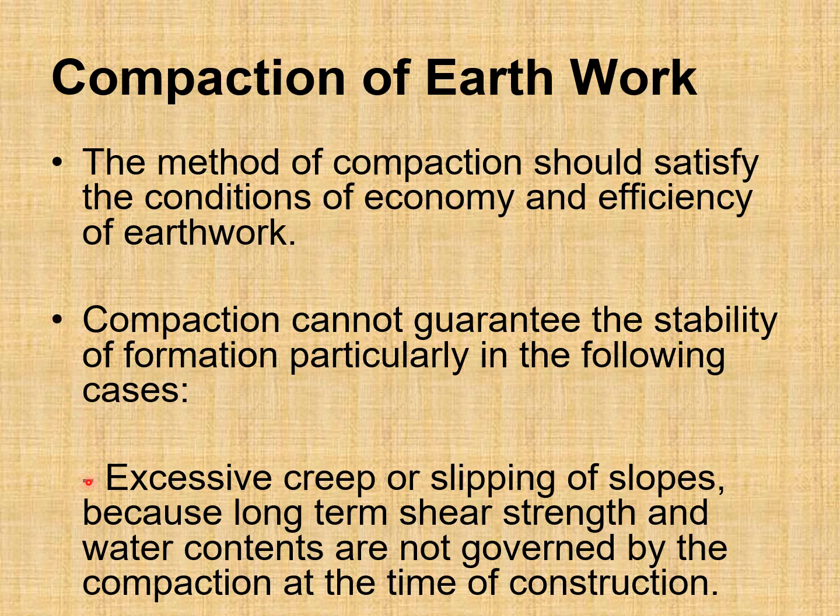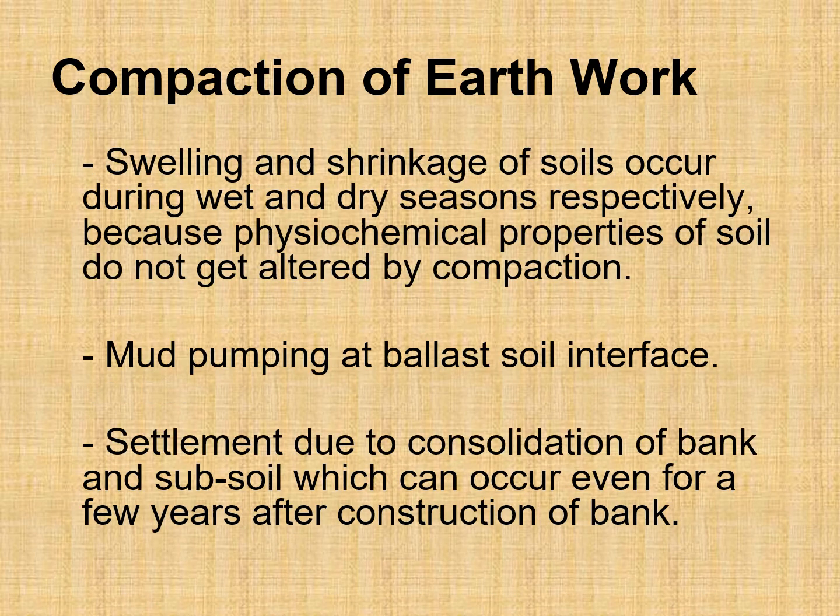Excessive creep or slipping of slopes, because long-term shear strength and water contents are not governed by the compaction at the time of construction. Swelling and shrinkage of soils occur during wet and dry seasons respectively, because physiochemical properties of soil do not get altered by compaction. Mud pumping at ballast soil interface.